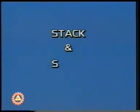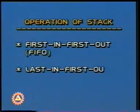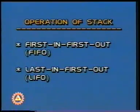The stack and stack pointer is used to save this information. The contents of the stack are the information to be saved, and the stack pointer points to the location where the information is stored. The stack is an array of registers and may be organized either as first in, first out FIFO or as a last in, first out LIFO manner.